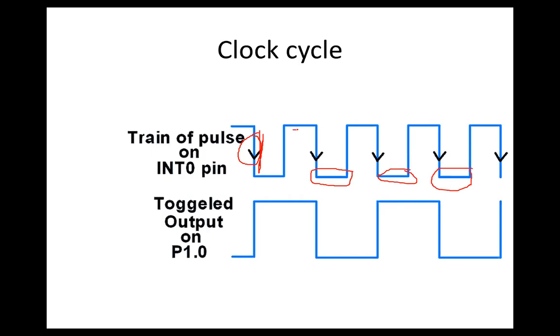If you are discussing flip-flops, you can give any clock pulses. You can give the clock pulses as a lower edge or a higher edge. You can give an edge trigger, meaning a positive edge trigger or a negative edge trigger. You can also give level triggering, positive level triggering and negative level triggering, in the flip-flop to change its state. You can give any triggering pulses to change the state.